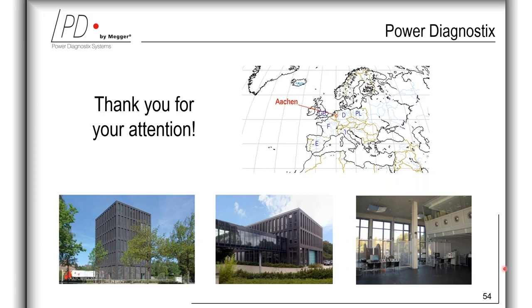Sebastian asked which equipment is mainly affected by partial discharge. Not easy to answer, but all kinds of electrical equipment where you have high electrical fields can show partial discharge and internal defects in insulation material. And it's not a question of the voltage level of the asset, it's a question of the internal electrical field strength, which is then causing partial discharge.